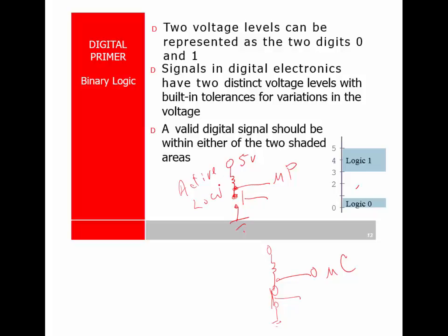When I push the button or close the sensor, I take the input voltage of the transistor from 5 volts to 0 volts. This one here is active high. When I push this button, I take it high. It's 0 normally. With the button closed, this is a short circuit to ground, and I'm measuring ground right there. So this is actually preferable.